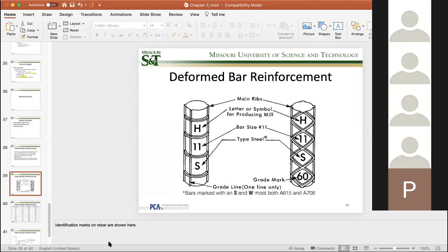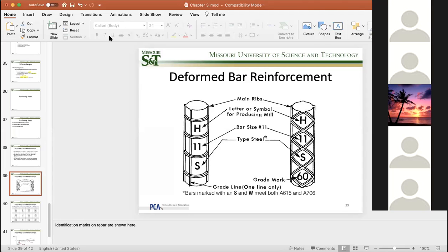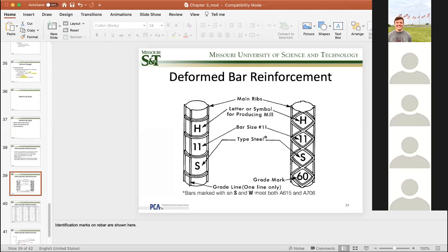Okay, so I'm going to call our next victim. Who's on here? I'm going to pick Dalton. You still there? Yes, I am. All right, great. So the question is, why do we have to have ribs in a rebar? My guess is so that it can adhere to the concrete better, so there's no slipping inside the concrete once it's placed. Exactly, right? The slipping, right?